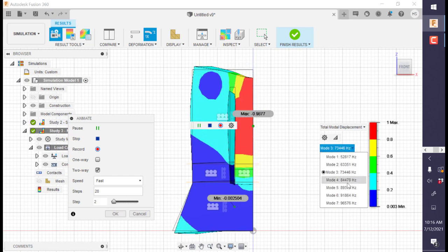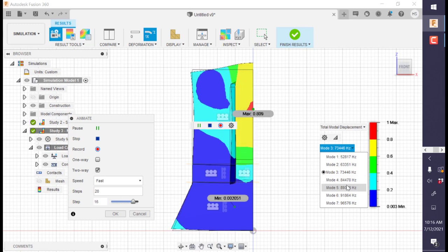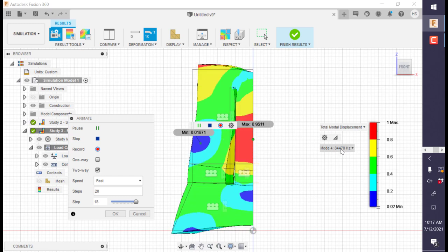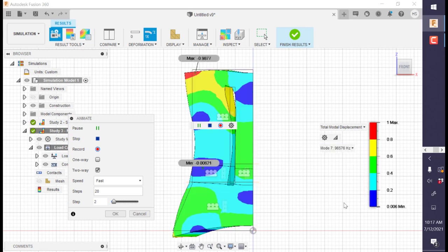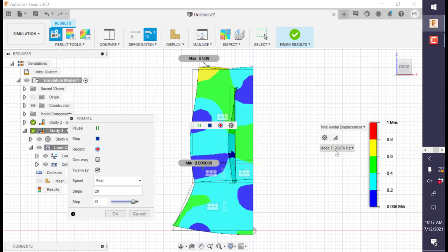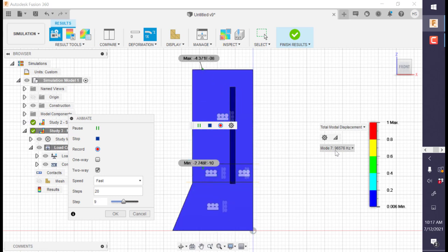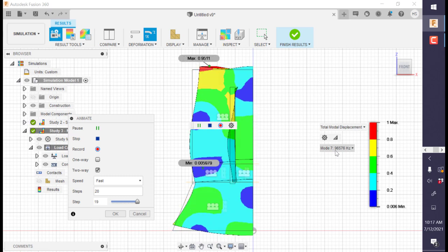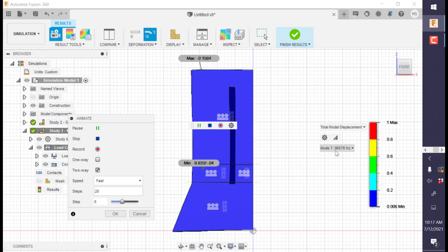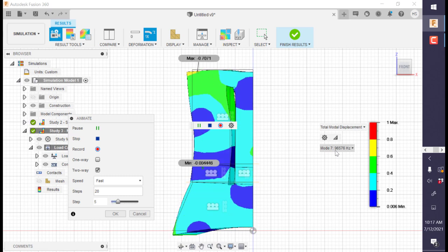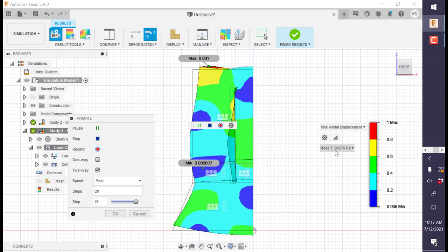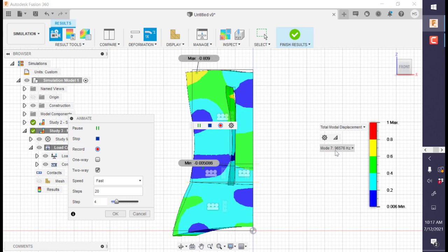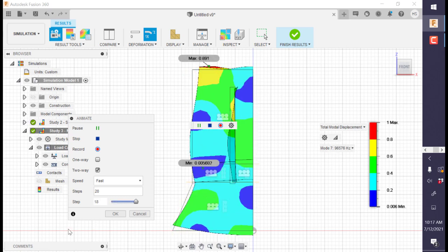And there are also numerous other modes. Technically, there's an infinite amount of modes which exist. Here's the mode at 84 kilohertz. Here's the mode at 95 kilohertz. As you start increasing in frequency, the wavelength decreases and the complexity of vibration increases. So typically, when you are having a higher frequency, either you are using a higher order mode or you simply just have a small device, which is appropriate then for the wavelength of resonance.